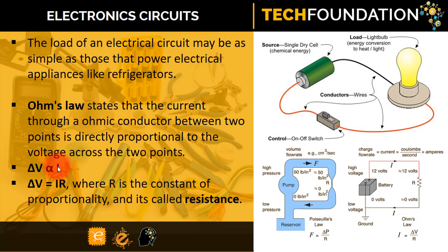A change in temperature has different effects on different materials. Some materials have what we call positive temperature coefficient of resistance. What this means is that as temperature increases, their resistance also increases. Others have a negative temperature coefficient of resistance, meaning that their resistance decreases as temperature increases. This is how a thermistor works. As the temperature increases, its resistance decreases, and we sense that and trigger some action.